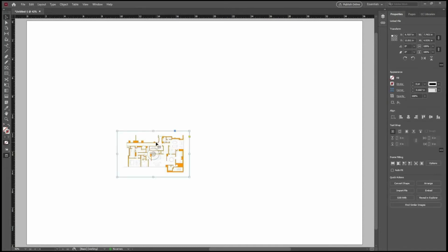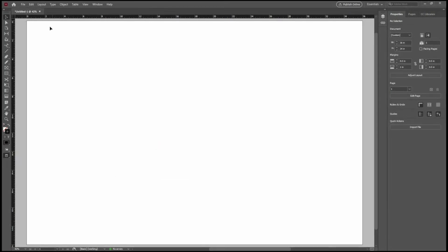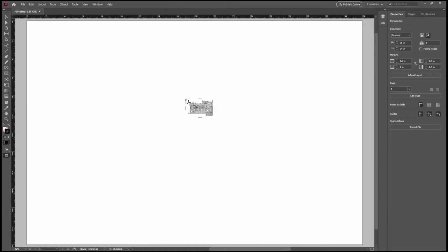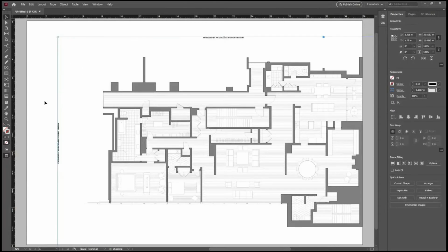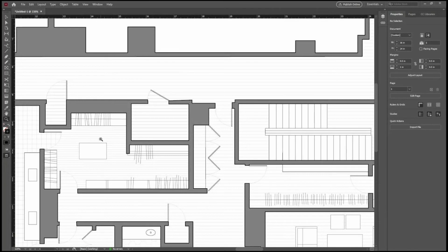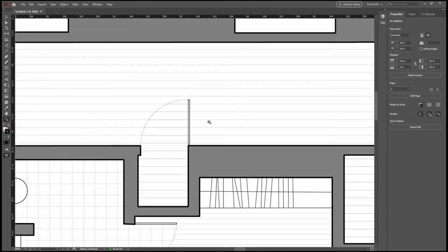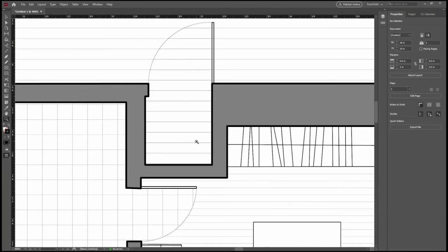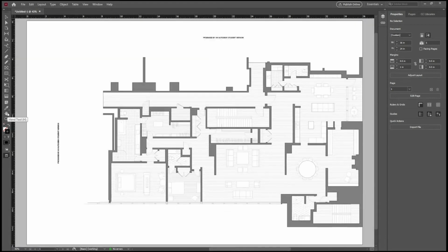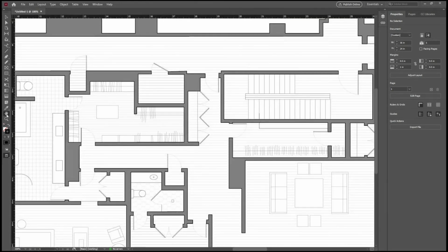Double click on the hand and zoom out. Choose the select tool, click delete. Now let's compare that to a file place of the actual PDF, which is here. Double click, click on the screen here, and when you use the magnifying glass, you again can see the PDF file is better quality. Look how sharp these lines are. They're no longer pixels. This is a vector file.